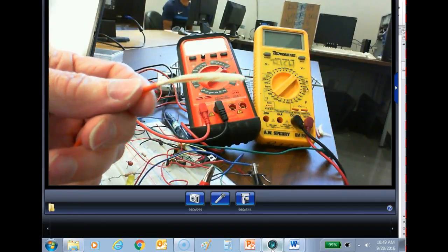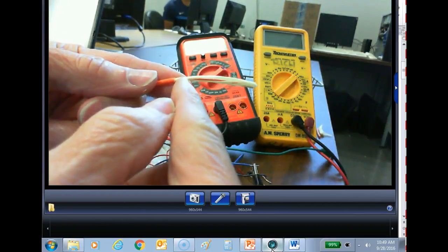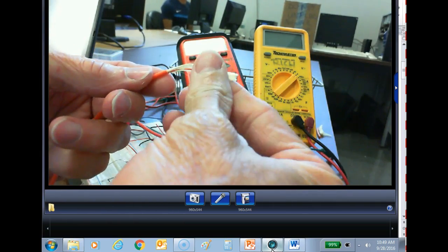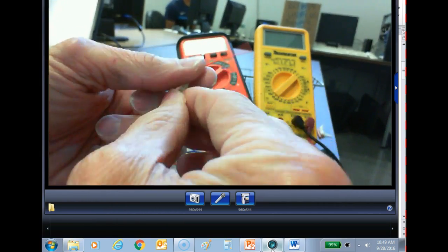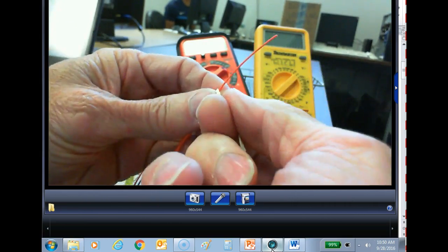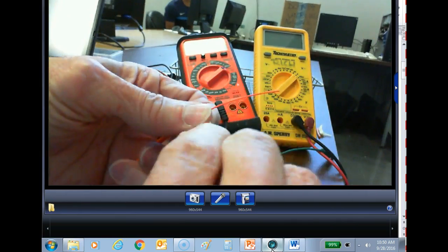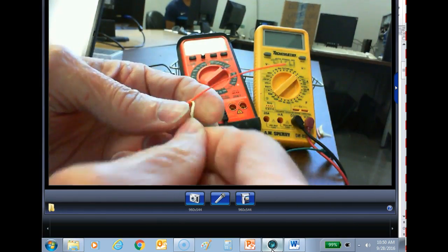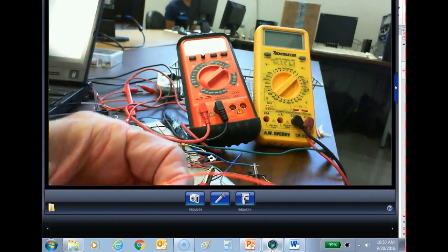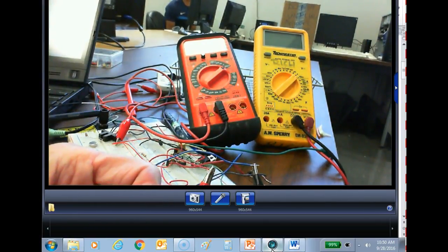Make sense? Then what you're going to do is get your template or your ruler, and mark where the Kevlar needs to go. You're going to take the Kevlar, pull it down to the side, and twist it. And once you get it twisted, mark where you want to cut it. Then you'll get your Kevlar scissors and cut it at that length.